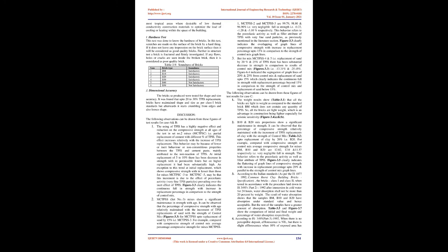The result of water absorption shows that the samples BM, B10 and B20 have absorption under standard value and hence acceptable. But the rest of the samples have a greater amount of absorption. Table 3.5 and figure 3.7 show the comparison of initial and final weight and percentage of water absorption respectively.